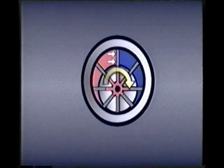As system pressure rises, the force applied to the vane increases, and the rotary force developed at the shaft, the torque, also increases. As long as the size of the motor remains the same, increasing the pressure will increase the torque. If pressure drops, torque drops. A similar relationship exists between flow rate and speed.